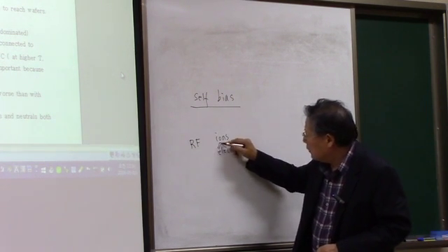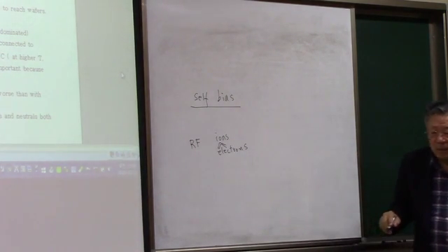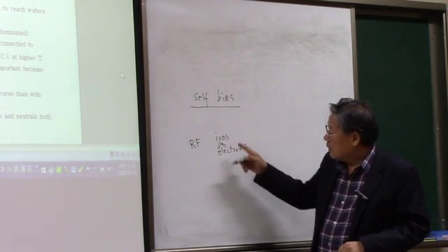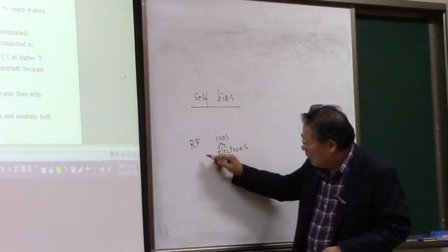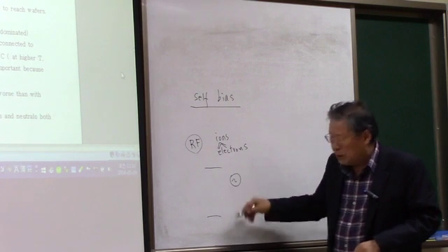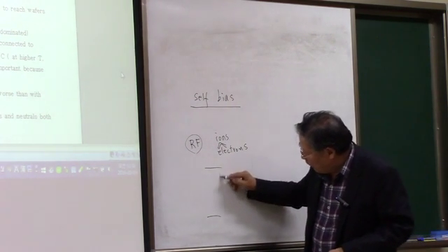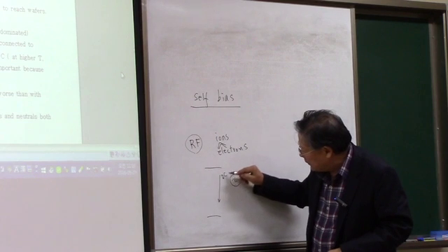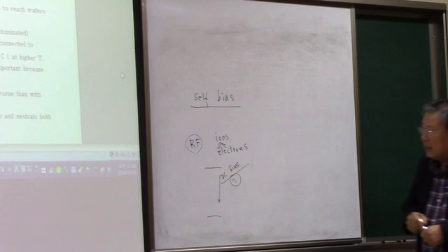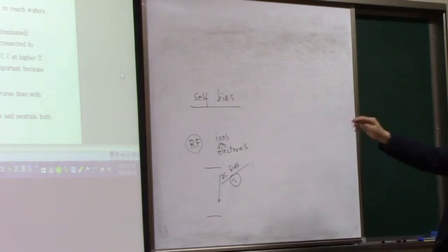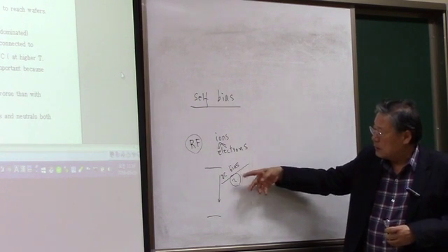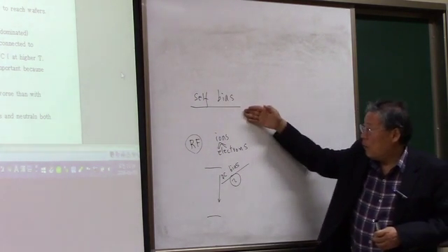The electron has a very high mobility compared to the ions, so even if you apply the AC between two electrodes, it forms a self-DC bias, okay, because of the difference in the mobility between ions and electrons.